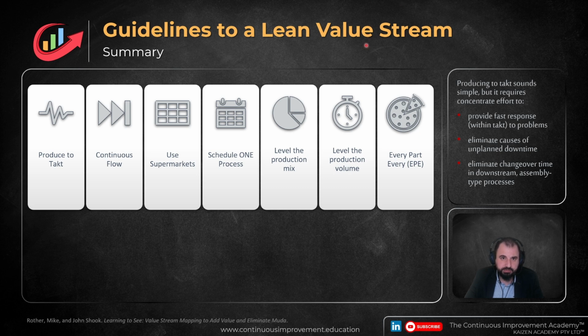Level the production mix, ensuring responsiveness to the varied customer needs. Level the production volume, creating predictable, consistent flow with paced withdrawal. And finally, strive for every part, every day, shift, or even hour by reducing changeover times.